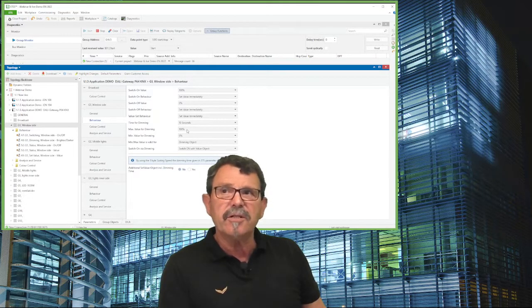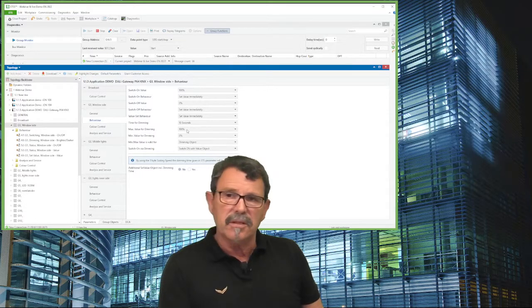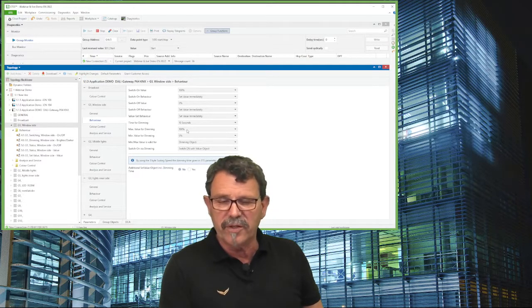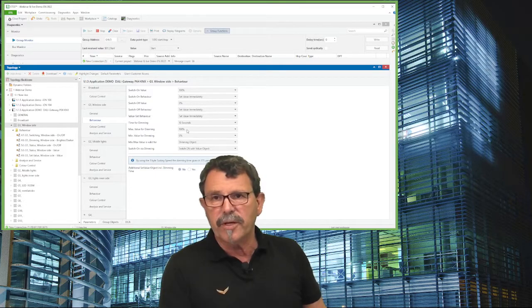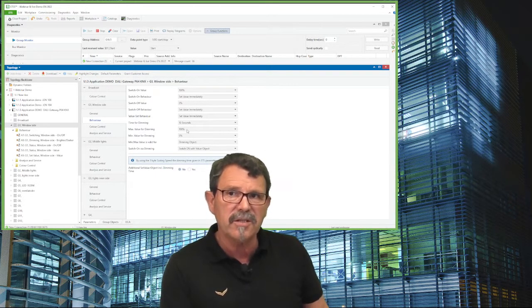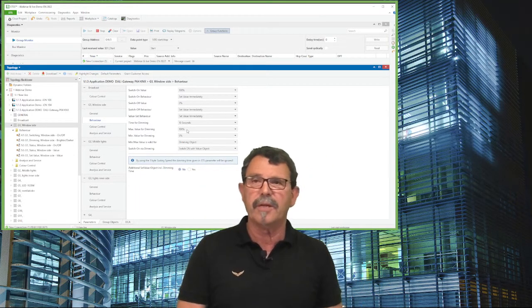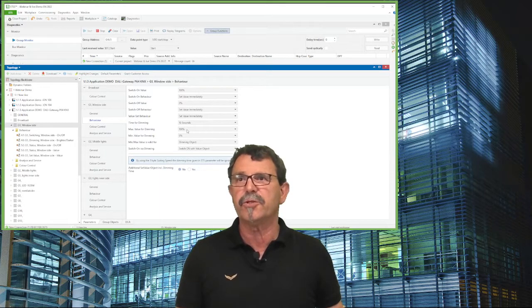So if you adjust here, for instance, the minimum brightness to 1%, but your light isn't able to support you. Some of these lights are stopping at approximately 5%, and then they switch off immediately, so don't wonder. Yeah, so this is a limitation from the light side, from the switchgear side.